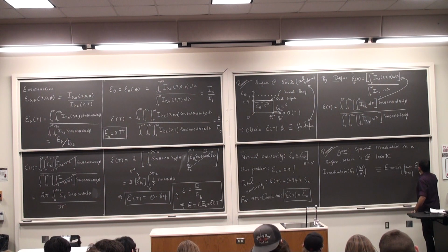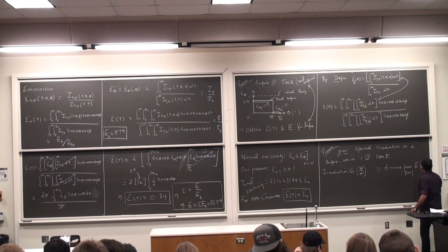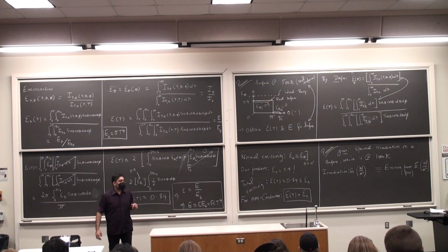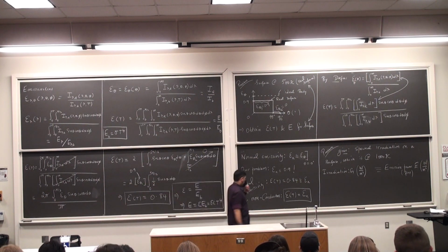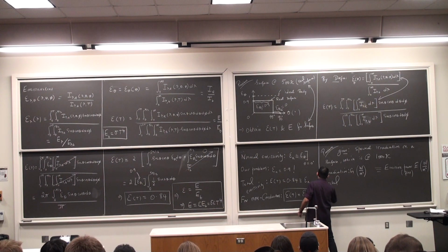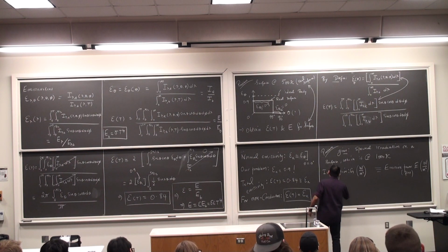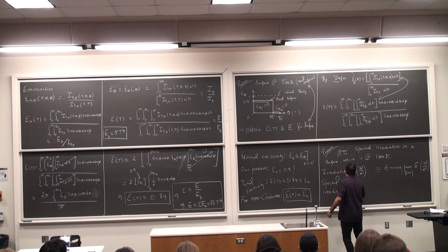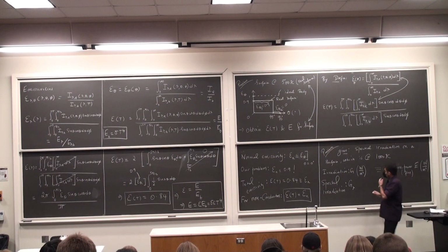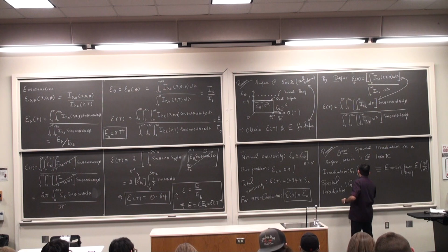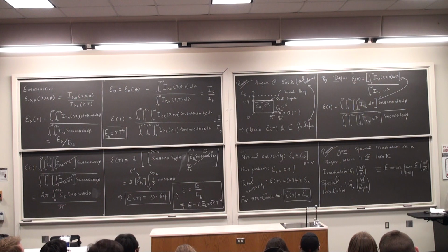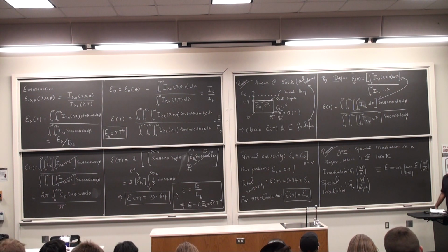Which is capital E, which is also watts per meter square. We have the spectral emissive power or the spectral emissive flux, whose counterpart in irradiation is the spectral irradiation. It's a spectral irradiation, which is G subscript lambda, okay, and so its units are going to be in watts per meter square micrometer. And if I take the spectral irradiation and integrate it over all the wavelengths, I get the total irradiation, capital G.